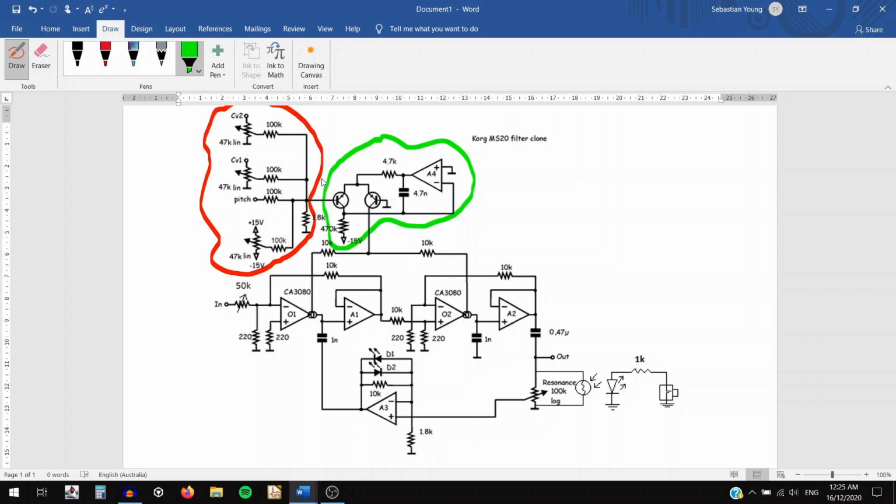This is also another reason why we can play the filter through the volt per octave input, due to our perceptions with frequency. As we have covered this part in the TTO, we don't need to go into the details again, but we should just note that these transistors here are PNP type, unlike the TTO LV tech, which uses NPN transistors. This is because it is designed to work as a current source, rather than a current sink.